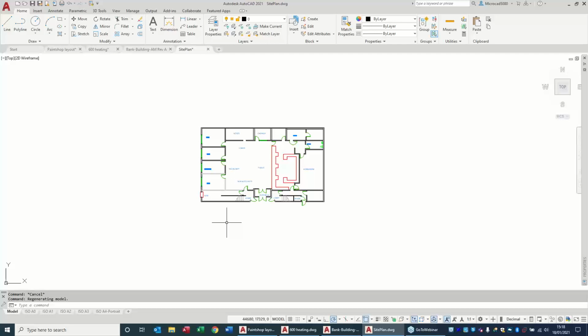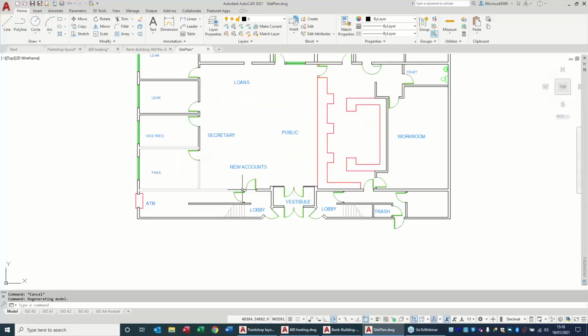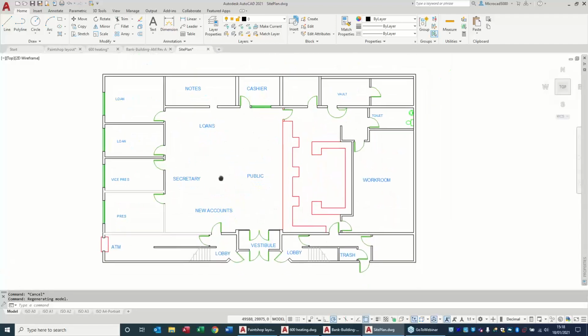The idea behind e-transmit is that it will transmit your drawing and send it out to anybody who needs your drawing file. Or if you're receiving drawing files, I've no doubt you've had the situation where it says Xref not found or can't find a font file. Now this e-transmit will cater for all of those and get around the issue of files missing.